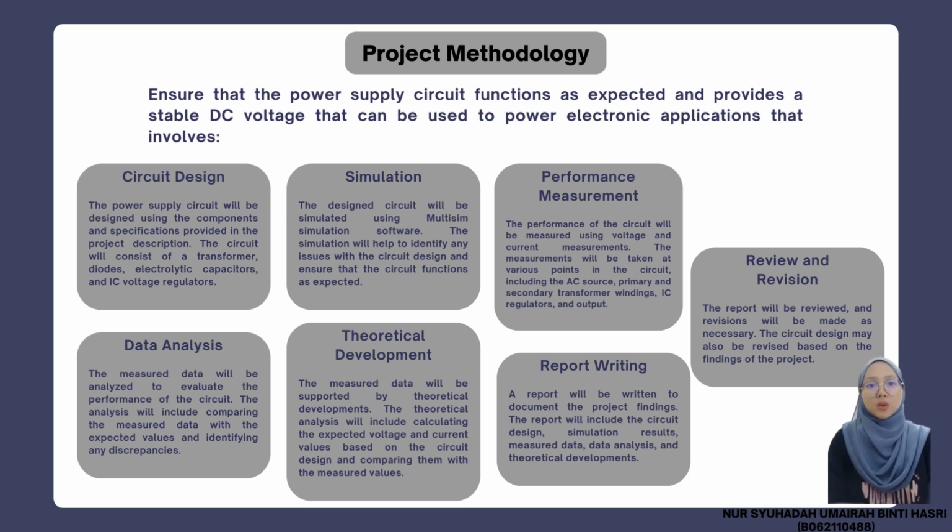Project methodology: ensure that the power supply circuit functions as expected and provides a stable DC voltage that can be used to power electronic applications. The design must include the transformer, diode, electrolytic capacitor and the IC voltage regulator. The circuit will be simulated using the Multisim software to identify any design issues, while the data analysis will be performed by comparing measured data with the expected value and identifying discrepancies.